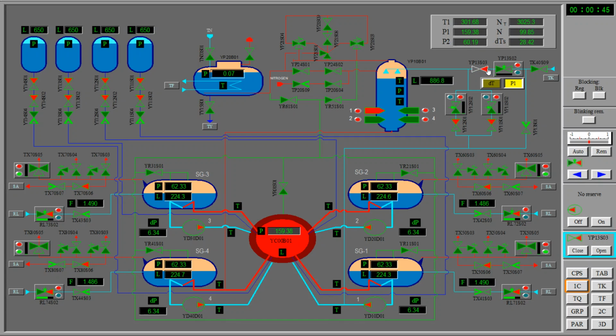So let's open the valve TK40S09, open, and let's remove the auto control of this variable valve and set it manually to some value, more or less 3/4 of the maximum aperture, maybe a bit more, we'll see. Now we are at 160 bar more or less, and it's decreasing fast.